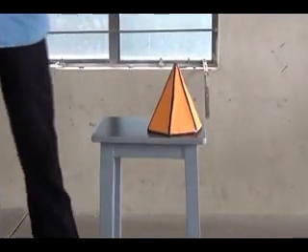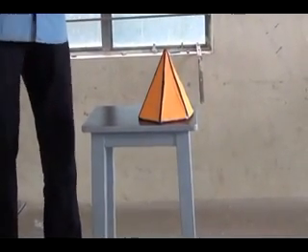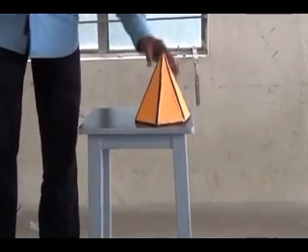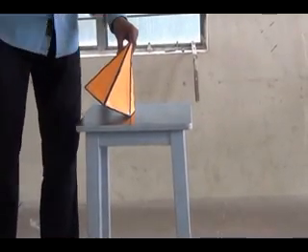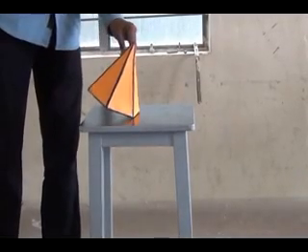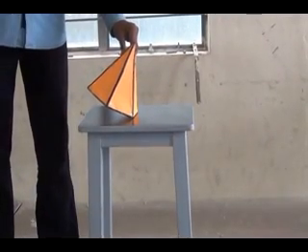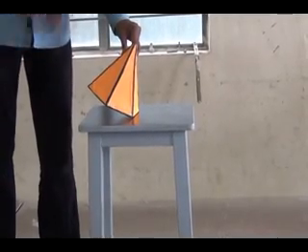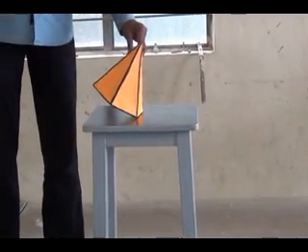If you consider a plane and keep it perpendicular to HP and perpendicular to VP, here the plane is nothing but the triangular face. The triangular face is like this, the face on which it is resting along the base edge. So that is perpendicular to VP and perpendicular to HP. This is the orientation. Now in this orientation, you look at the solid's axis. How is it? The solid's axis is inclined to which plane? HP.